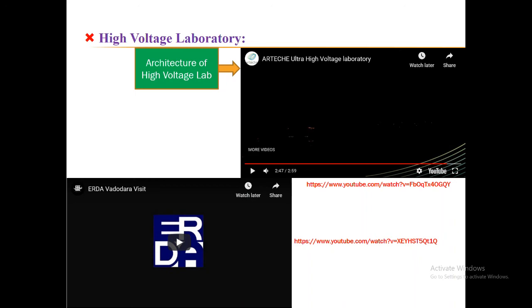So when you are performing the impulse voltage test, you need to capture those impulses by using this DSO, potential divider circuit, along with the CRO. The output is normally given to the laptop or the computer on which you can capture the wave shape and analyze it to reach a decision.